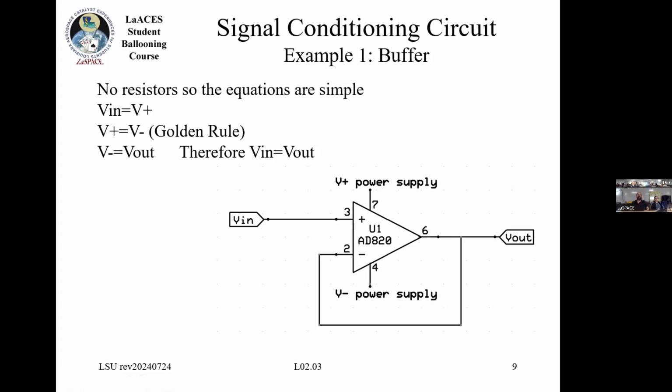So this is a circuit that has a gain of 1, right? Basically the output should be equal to the input, but the reason you build something like this is, like I said, because you usually want to isolate whatever your input is from your output. Like this is maybe a super sensitive sensor, and then you have some output that you're trying to drive that needs a lot of current. So in this case, all the current comes from here, and you don't mess up the thing that's driving.